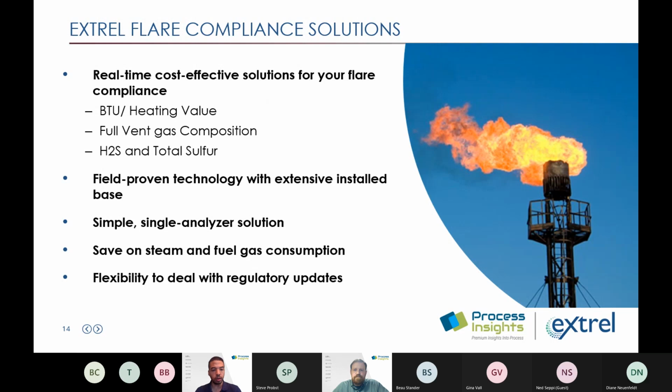They were interested in hearing what all would be required to bring the analyzer into compliance, what updates they would need to make. So I got some information back from them about their current software configuration and their current analysis setup, and took a look. I identified some additional compounds that they would need to measure, and had some discussions with them about that. And then we also talked about the additional standards that would be required for their quality checks.